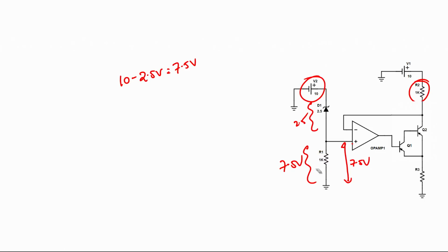But why a 1K resistor, why not some other value, why not 10 ohm, why not 1 ohm? The reason for going with the higher resistance value is that when we look into the data sheet of Zener diodes or any semiconductor based system, they always provide the information of the maximum current it can withstand, the operating current.